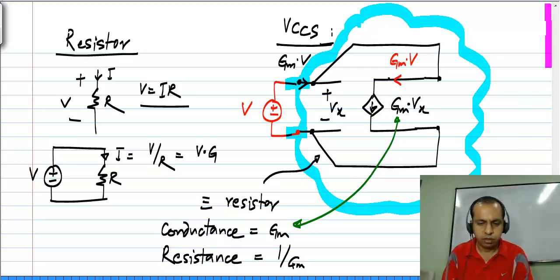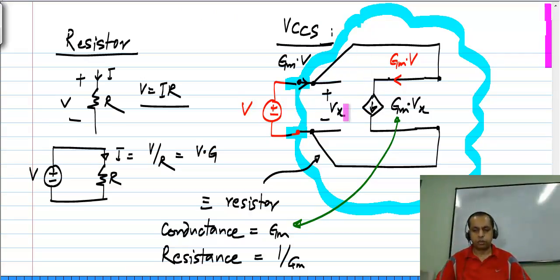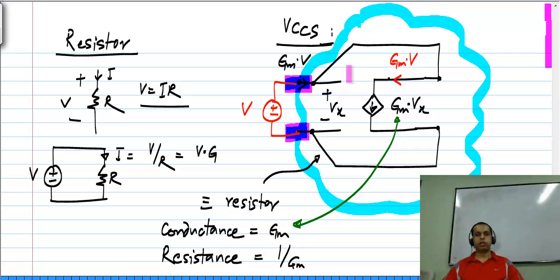So what do we have here really? We have a voltage controlled current source, and the controlled current is connected back to the controlling terminals. So we end up with a two terminal element. There are only these two terminals, and between these terminals there is a linear relationship between current and voltage.